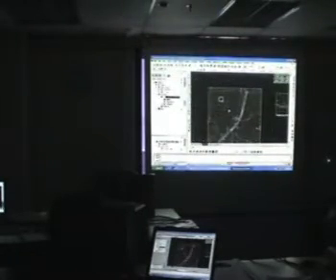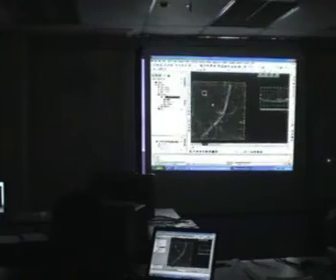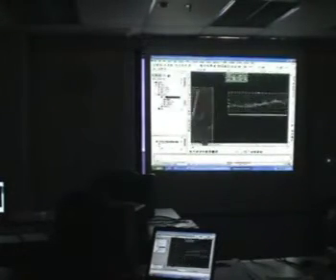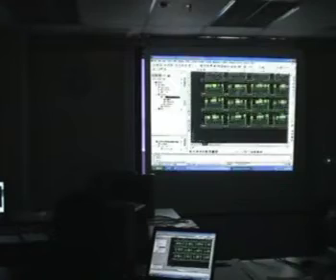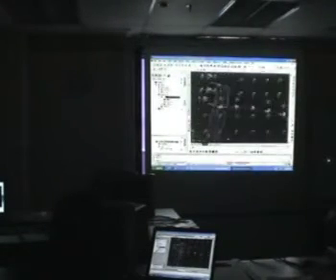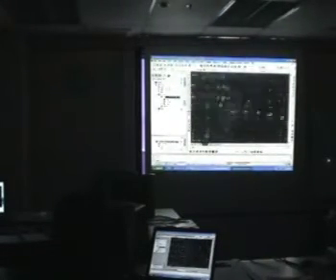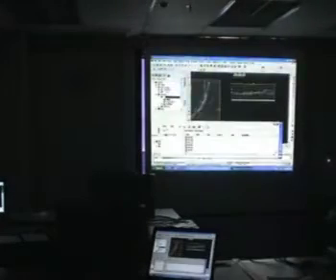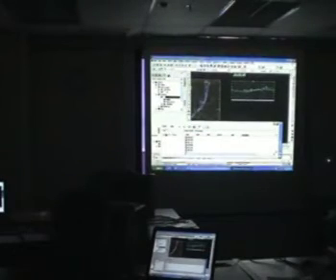Now coming back to the object, what we call the dynamic abilities of Civil 3D. I have already created a road here. We've got a horizontal profile and a vertical profile. We've even got some cross sections in here. So I'm just going to click here, so get hold of my horizontal alignment. I want you to look at the vertical. You can see the vertical has been adjusted automatically.